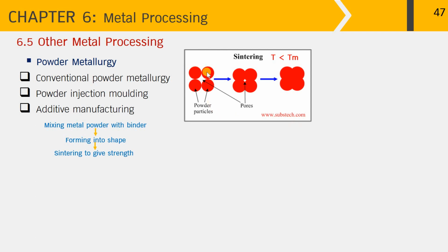We're starting with metal powder as the particles packing close together. Once we increase the temperature towards the right hand side, necks begin to form along the boundary of the particles, and that makes the pore size reduce significantly. Further increase in temperature will completely get rid of porosity, so we can have the density of the sintered product up to more than 95% of theoretical density.